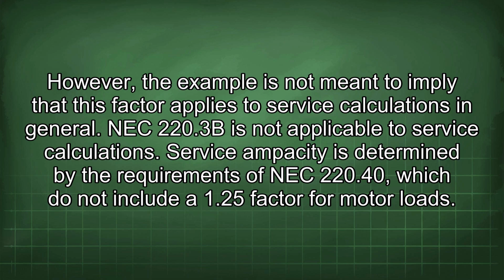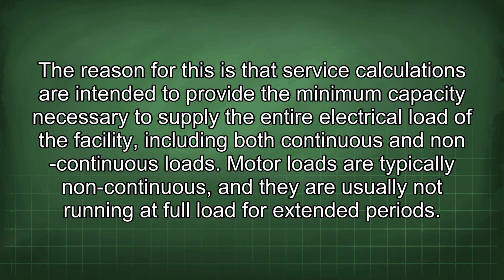NEC 220.3B is not applicable to service calculations. Service ampacity is determined by the requirements of NEC 220.40, which do not include a 1.25 factor for motor loads. The reason for this is that service calculations are intended to provide the minimum capacity necessary to supply the entire electrical load of the facility, including both continuous and non-continuous loads.